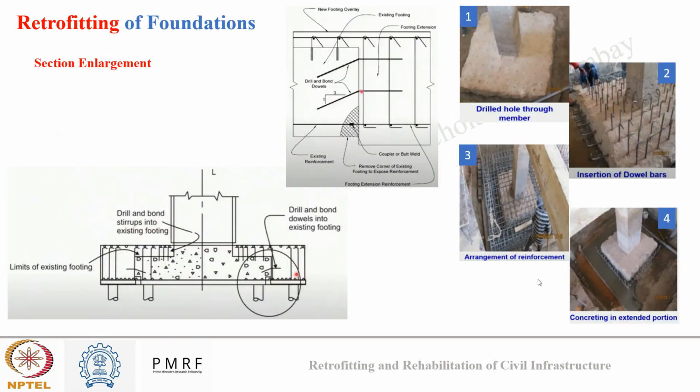Okay. So till now we talked about strengthening of structural members above ground: columns, beams, walls, and slabs. Let's talk about strengthening of foundation now. If we recall our discussion from the basics of structural engineering, the load is transferred from slabs to beams to columns and then to the foundation, which then transfers the load to the underneath soil.